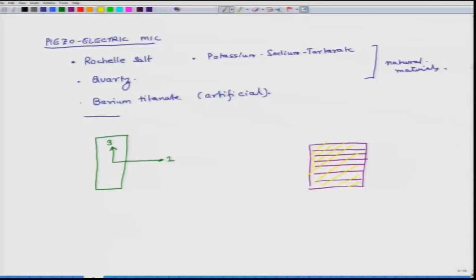So, a sheet of cloth has all the fibers in one particular direction and they are bonded together by this glue. When I look at the structure, fibers are in one particular direction, I can call this direction 1, because this is the direction of the material, and I can call the other direction 3 and the perpendicular direction 2.